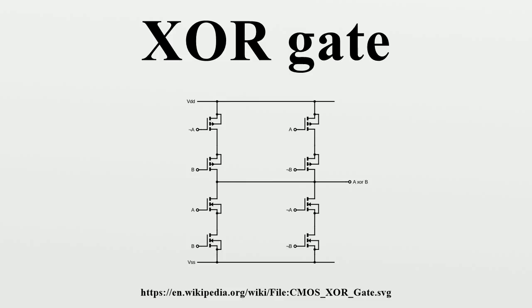In fact, both NAND and NOR gates are so-called universal gates, and any logical function can be constructed from either NAND logic or NOR logic alone. As an alternative, if different gates are available, we can apply Boolean algebra to transform the expression as stated above, and apply De Morgan's law to the last term to get an expression which can be implemented using only 3 gates as shown below.